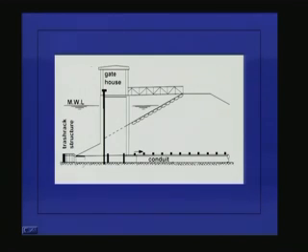The water enters the intake structure and then it goes through the conduit to the treatment works, and I can have a pump house here if it is required, but the main point is water enters into this conduit or into this intake structure through only one port, and we have a trash rack structure here which will prevent the entry of debris into this conduit, and this entry port is kept at the bottom of the reservoir, and so the water can enter into this conduit even when the water level in the reservoir is very low.